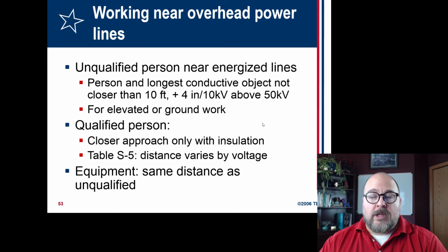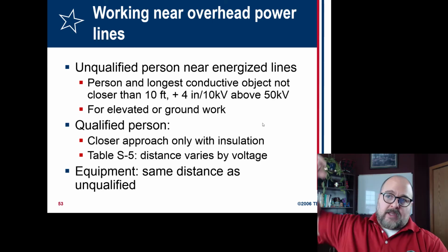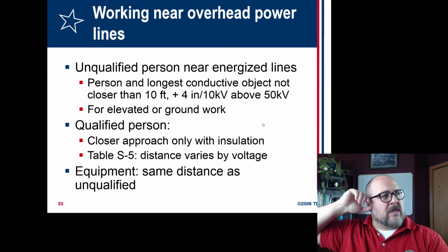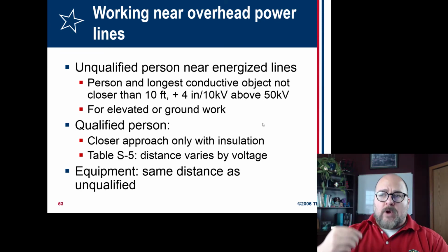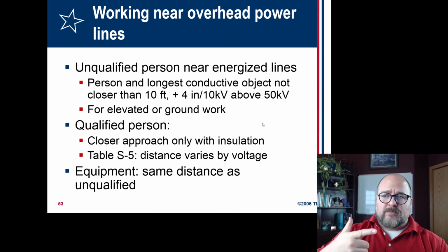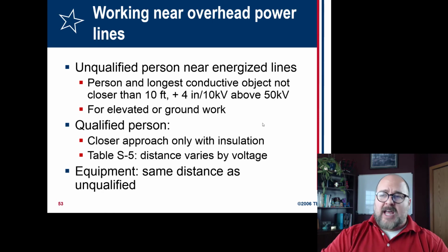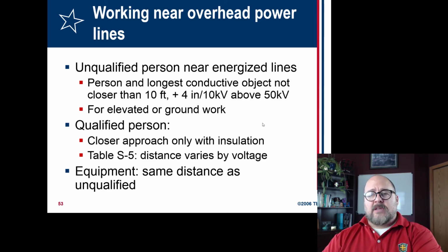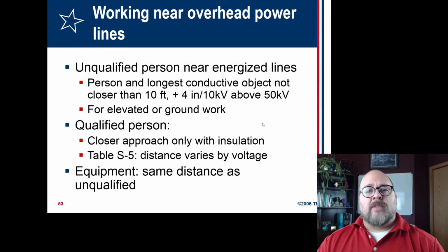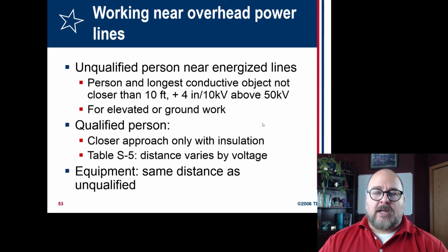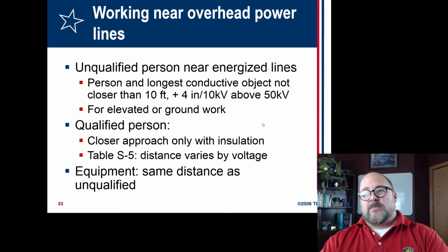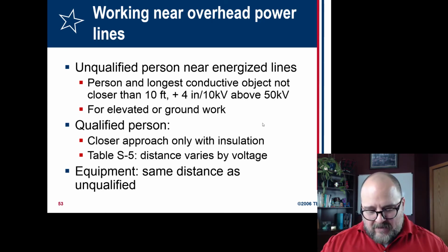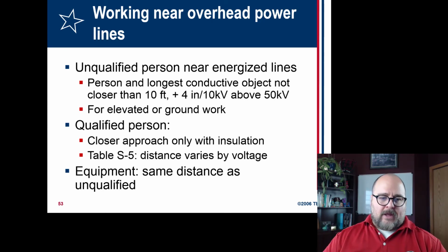If you're ever at a home and you've got an entry point that comes from an overhead line into the house, mine is underground. If you ever have to do work on the house, such as siding or your gutters or whatever it might be, contact your local utility and ask them to put protection on that line, just so you don't accidentally contact it. I mean, you may not contact it, but maybe the ladder slips or you drop a tool or something. Never ever go near it. Stay 10 feet away.